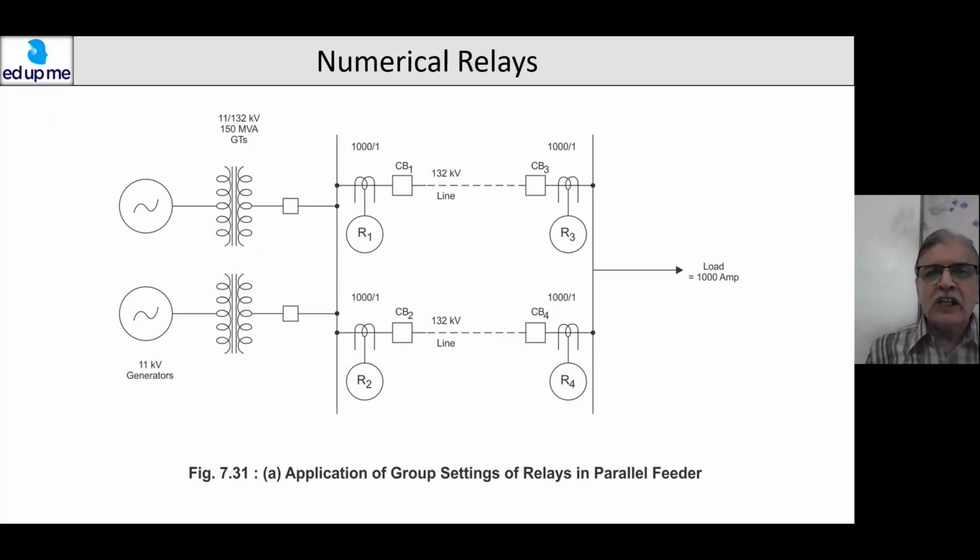And I am talking about only two buses and two lines. In an interconnected system, there are 50 transmission lines and many buses. So obviously the number of permutations and combinations is many more. And in these conditions, your relay has to match the newer requirement. Nowadays, modern numerical relay manufacturers, very renowned relay manufacturers, give us as many as 6 groups of settings.